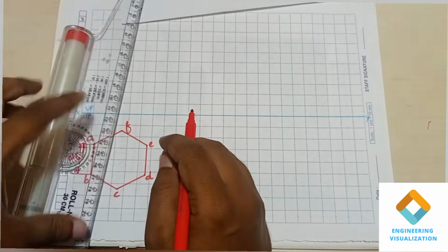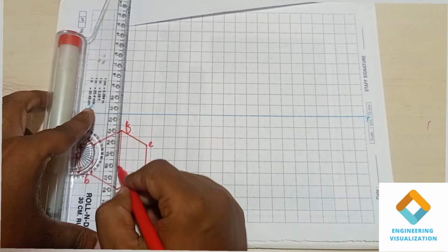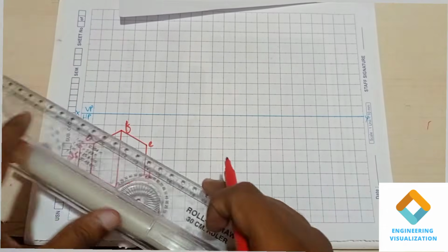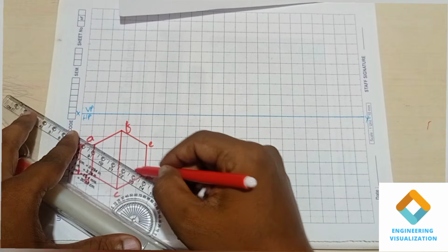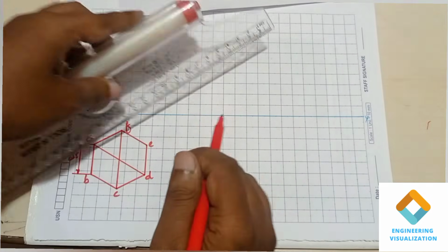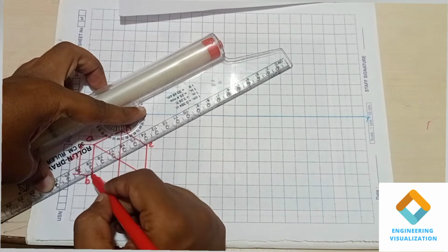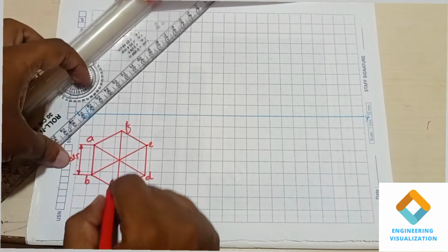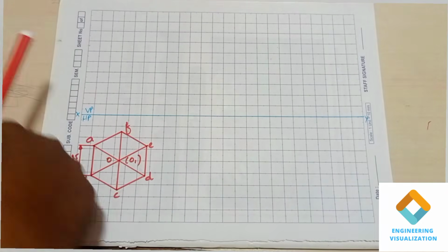So inside of this, since it is a pyramid, we have to show the slant edges. It should be thick lined. Okay, so draw the thick lines. That is drawing the diagonals. We get the thick lines here. And mark the center of the axis O1.